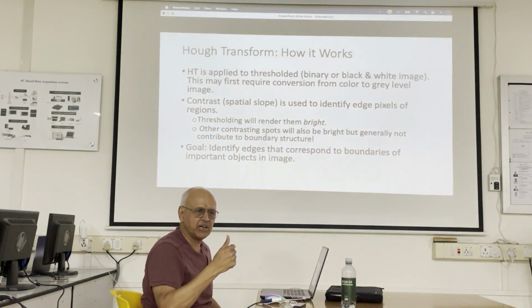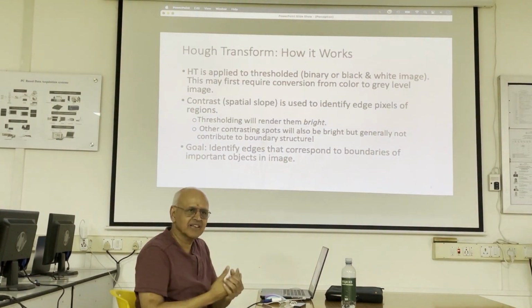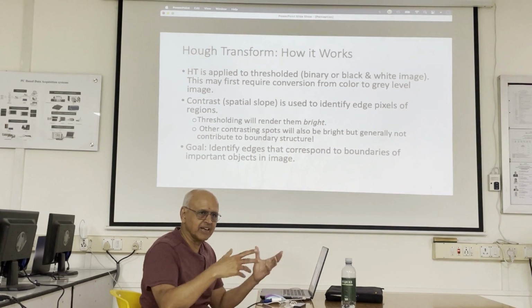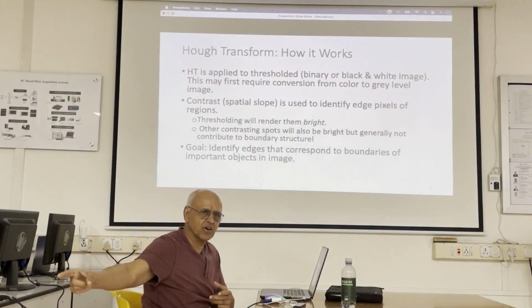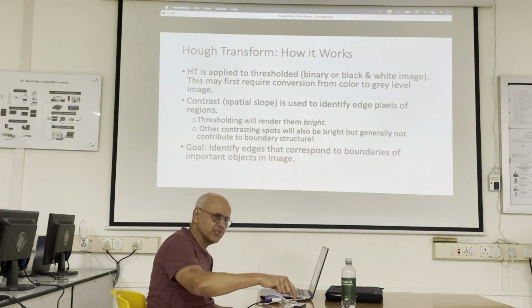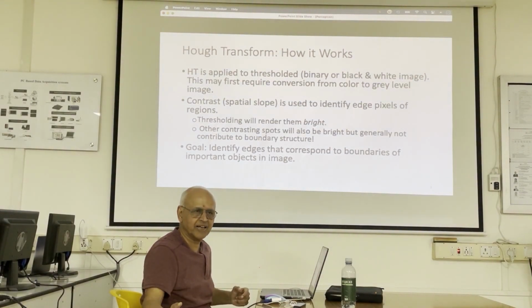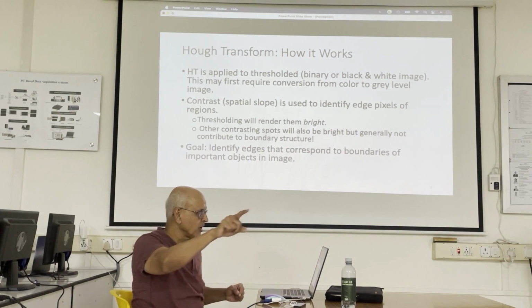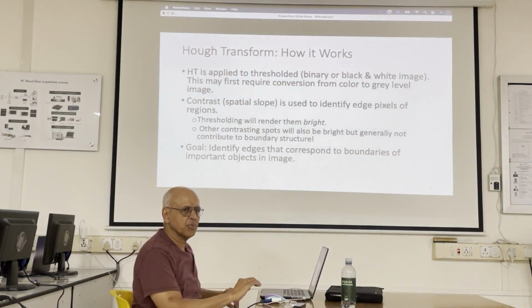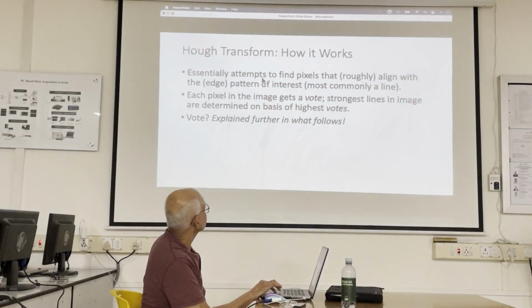So our eyes are basically doing that, except that we don't do derivatives. There's something going on in the brain that does similar things. But the computer has to be given an algorithm. You can't tell the computer to go copy this guy because it'll say how, right? So that's what it's doing. It's picking up spatial derivatives. Spatial means not with respect to time, but with respect to space. So you can go across the image and say, is there a change? And that's how you pick out the lane lines, or the contrasting spots.